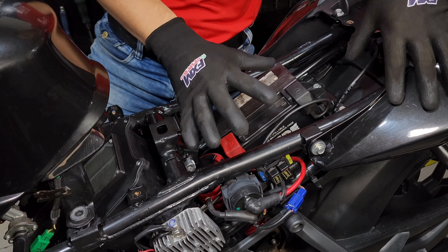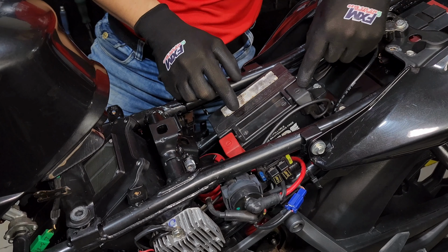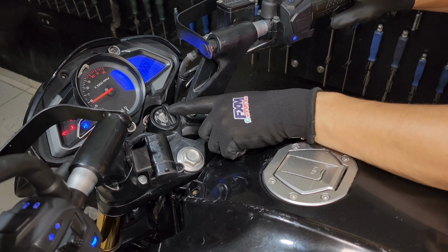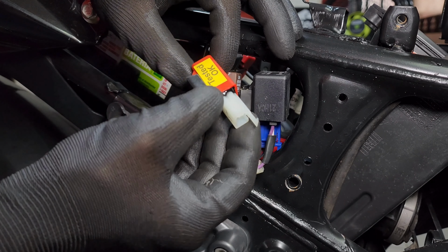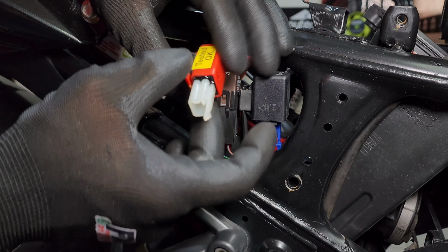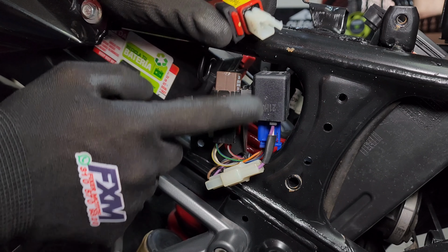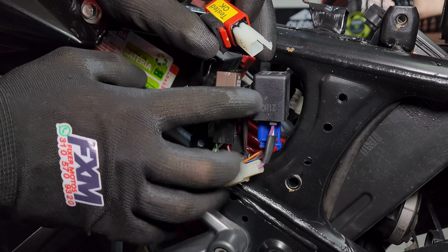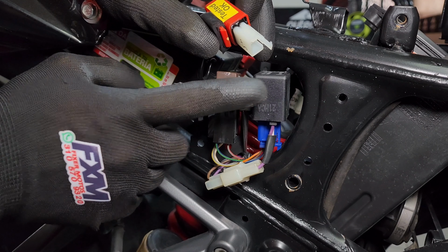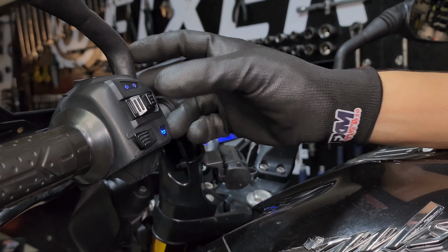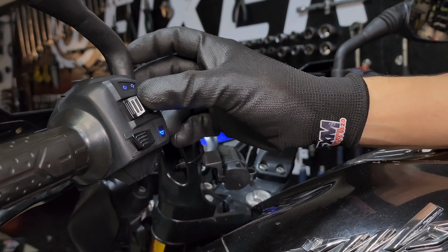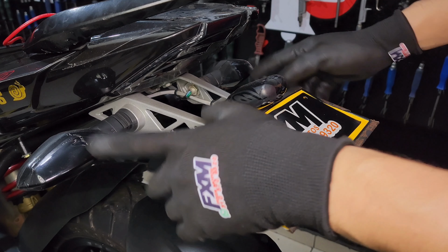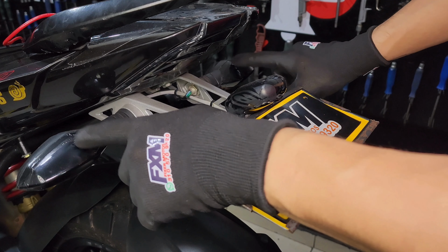So as I said at the beginning of the video, here we have the components. So we have the battery, the fuse box, the main switch. Normally in the carburetor model we will find a flasher like this, but in this model of motorcycle it is integrated into the light control unit, just like in the diagram we saw for the PULSAR 200 fuel injection. The left command that has the button for the turn signals, the indicator on the instrument panel, and finally the 4 turn signals, the 2 fronts and the 2 rear.